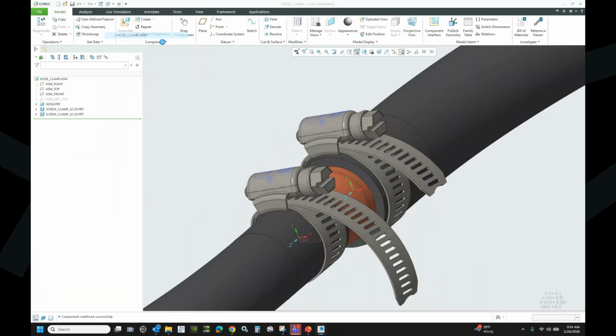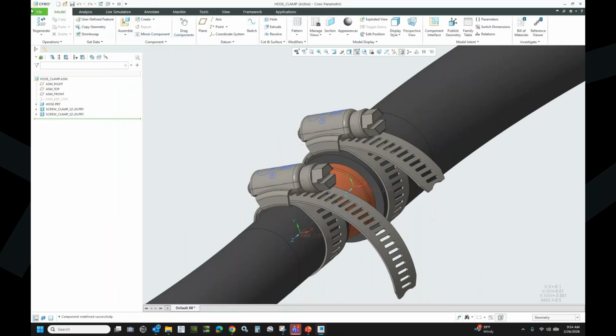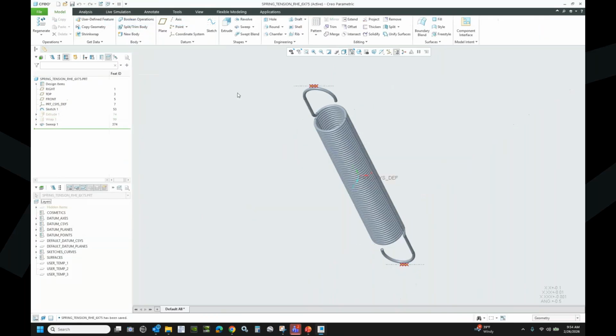When you were assembling the spring, you were adding the flexibility each time it was added. Can we add the flexible features to the spring and store it that way so every time we assemble it, it will have the option to use the flexibility? Yes, absolutely. Now, I don't personally like to do that for my models, but yes, you absolutely can do that.